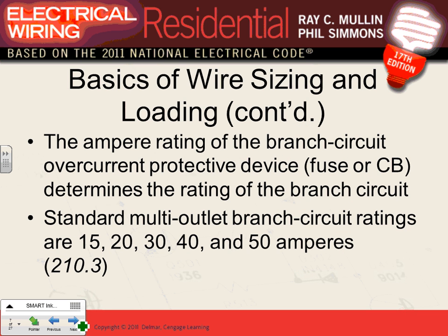As long as we're here, since we're doing residential, I would like you guys to get used to these very, very important branch circuits that we use in residential. The first branch circuit is the 15 amp branch circuit. With a 15 amp branch circuit, this one always goes with number 14, period.